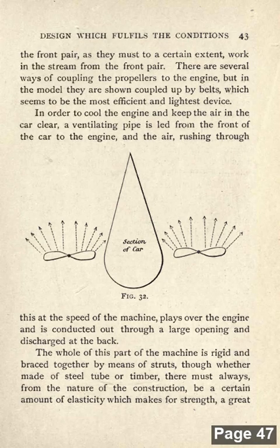In order to cool the engine and keep the air in the car clear, a ventilating pipe is led from the front of the car to the engine, and the air rushing through this at the speed of the machine plays over the engine and is conducted out through a large opening and discharged at the back.